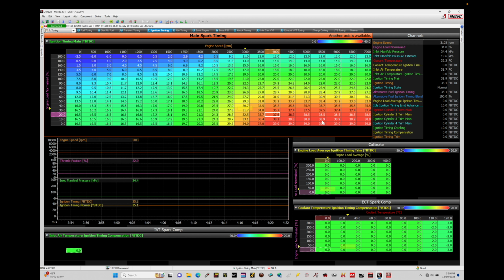So as we're looking at the table, we're going to find it has this shape where we have lower spark timing here at low engine speeds. As engine speed increases, we see the spark timing advances, and as engine load increases, the spark timing retards, or gets lower, or gets closer to that 0 degree mark that we're finding here. Now, if we have negative values in our table, this is going to be firing off our spark event on our power stroke. This would still be BTDC referenced, but we're actually initiating that spark event to happen after top dead center, relative to that power stroke. So we can see how this table is shaped. We need to consider what values we place in here and what kind of breakpoint axes we're dealing with.